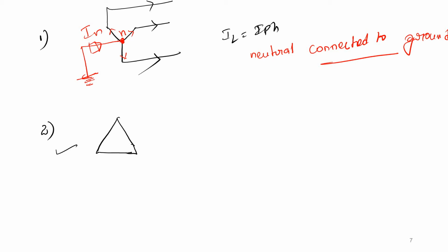That means you should give two conditions: one where the current will enter, and one where the current will not enter. You should have a switch. If the neutral is grounded, current will flow in the system. If the neutral is ungrounded, the switch should remain open because there is no entry for the zero sequence currents in the star connection.